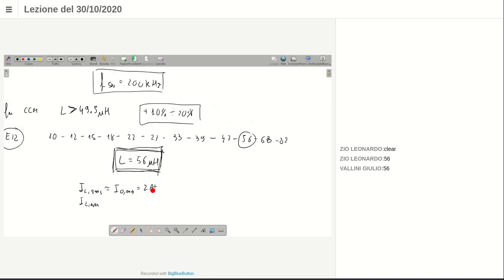Okay, this is true just for the buck converter in CCM, because for other converters with different waveforms, or in discontinuous conduction mode, of course, the RMS component can be much larger than the DC component. But for the buck converter in CCM, this could be a reasonable assumption.